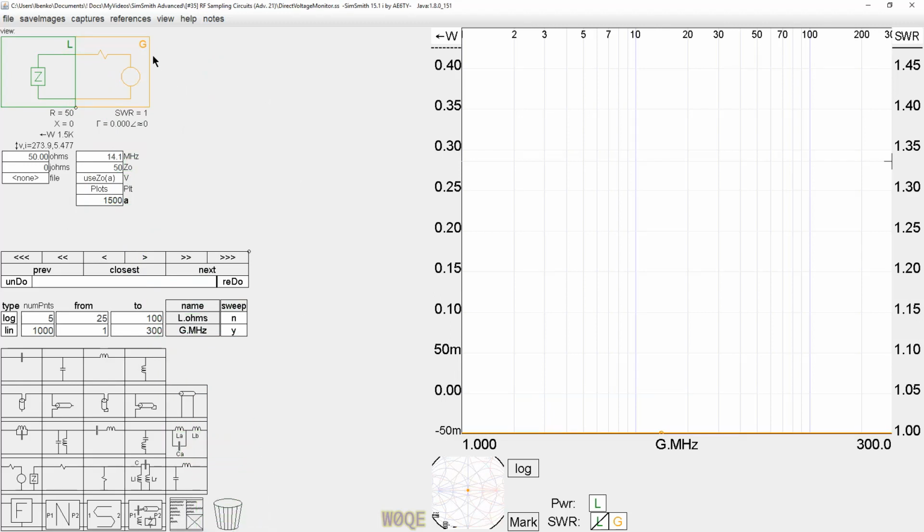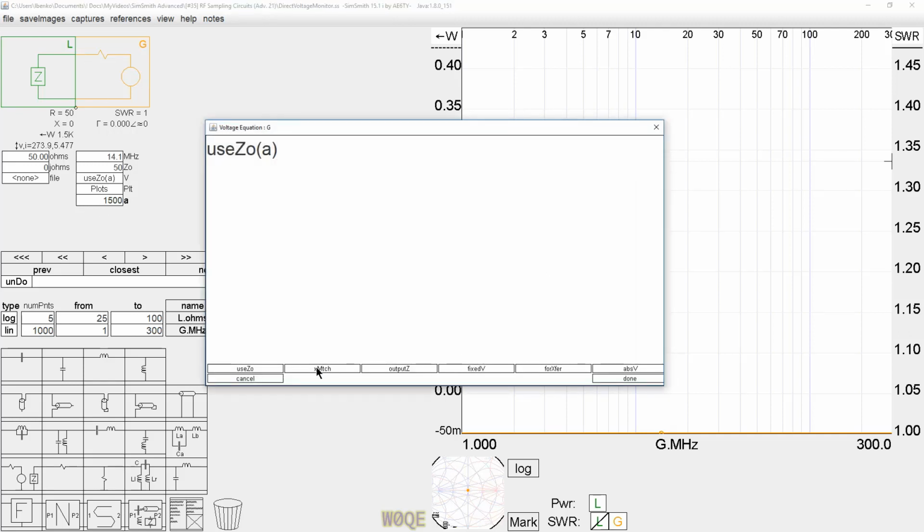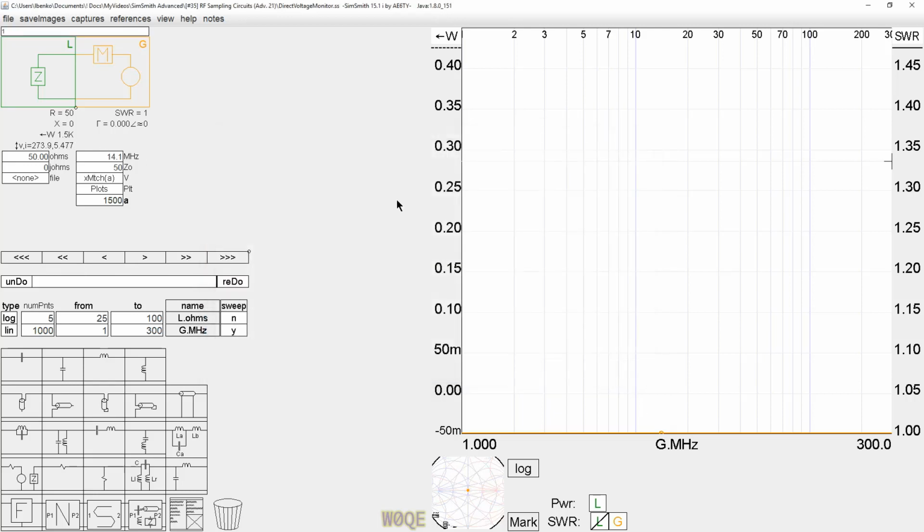Now, while we're doing this, I showed a circuit before that was two SO239 connectors butted up together with just a short piece of wire in between them, and I mentioned that you could use an oscilloscope to monitor the voltage. Well, let's look at that for a moment. The voltage we'd see here, as we calculated before, with a 1,500 watt load of type X match, so that we are actually matching to the impedance and get the full power out, shows 1.5 kilowatts in a 150 ohm resistor, and it shows us as having 474 volts here, which is what we calculated before.